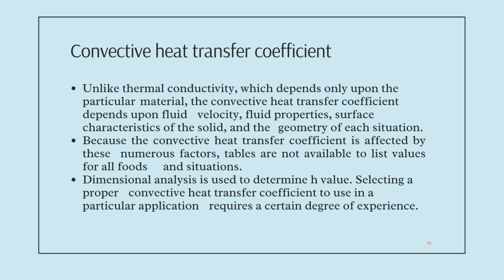Moving to next slide. Convective heat transfer coefficient continued. Unlike thermal conductivity, this value depends on fluid speed, fluid properties, surface texture, and object shape. There are no standard values for all situations. Dimensional analysis is used to estimate it, and experience helps choose the correct value in real applications.